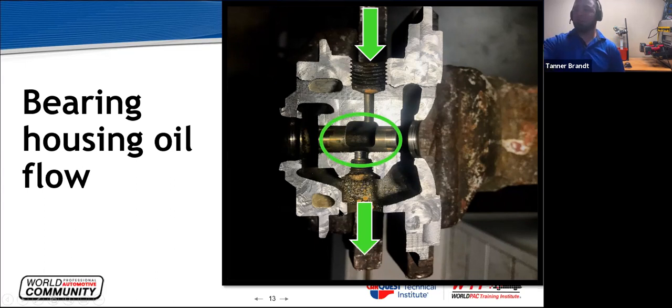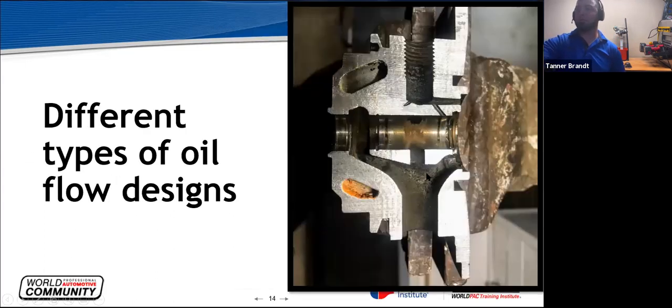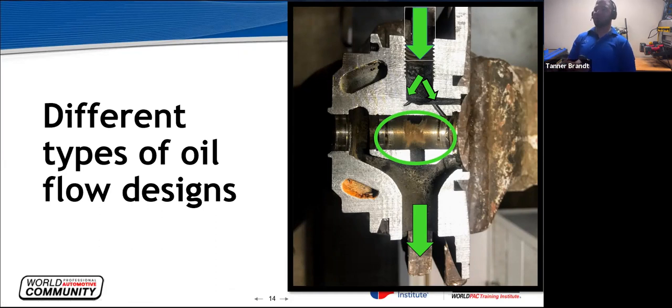The other thing that can happen is, this is another type, you can see it come through here, drain here and here, goes through your drain, and then comes out here. The other thing that can happen, though, is let's say you have high crankcase pressure. Imagine trying to blow through a straw held up to your mouth, trying to blow water through it, and somebody walks up with an air hose and sticks it in the end of the straw and puts 120 psi in it. It's obviously going to blow back at you.